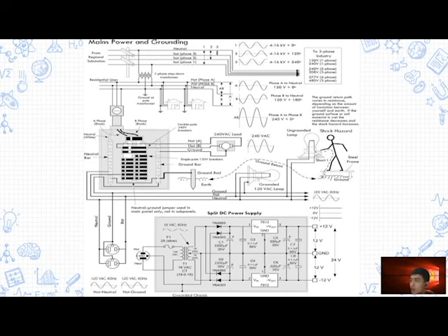If you want to supply 240 volts to a water heater, you insert a double pole breaker between the A phase and B phase bars in the main panel. Next, take a 240 volt 3-wire cable and attach one of its hot wires to the A phase terminal of the breaker and attach its other hot wire to the B phase terminal of the breaker.